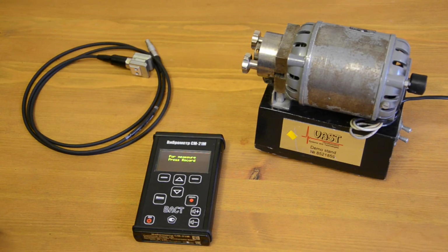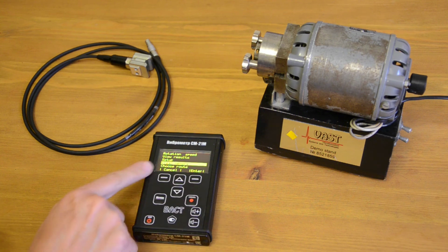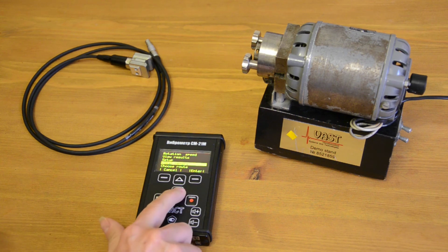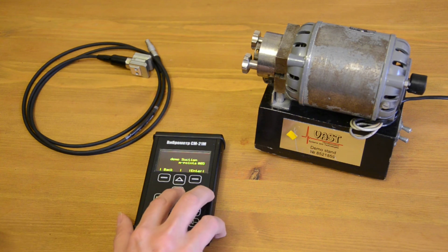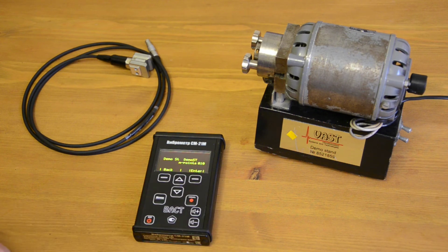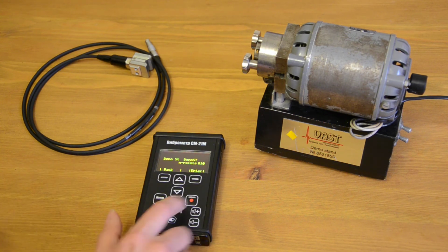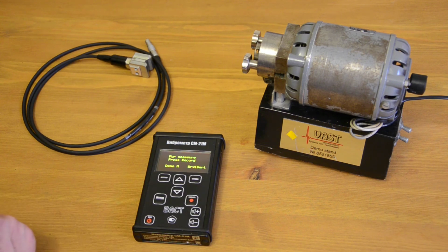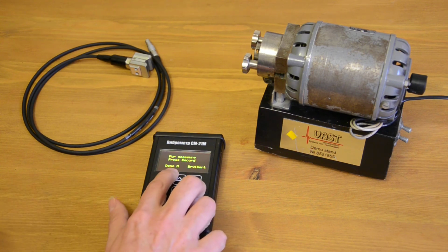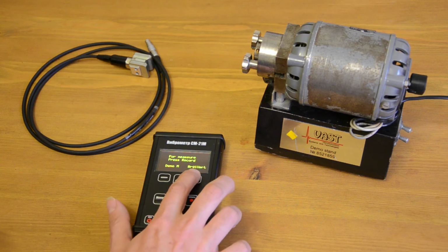So once we created the route and downloaded it to the data collector, we need to select it. We go to the menu, use the choose route command, choose route, and select our route. We have created a route that was called demo station. So this is demo station with 10 measurement points, and we select enter, and this is our route. So we have demo machine and bearing vertical.